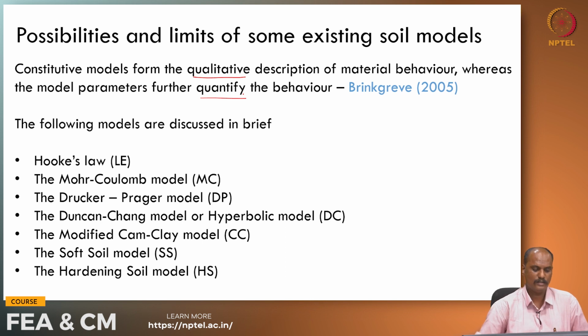We would start the discussion right from Hooke's law, based on the limit equilibrium analysis, the most famous linear elastic perfectly plastic Mohr-Coulomb model, the Drucker-Prager model, DP model, the Duncan-Chang model or the hyperbolic model. Then when it comes to soft clays, we have the modified Cam-Clay type of model from UK, and then the soft soil model, SS model, and the hardening soil model, called the HS model.